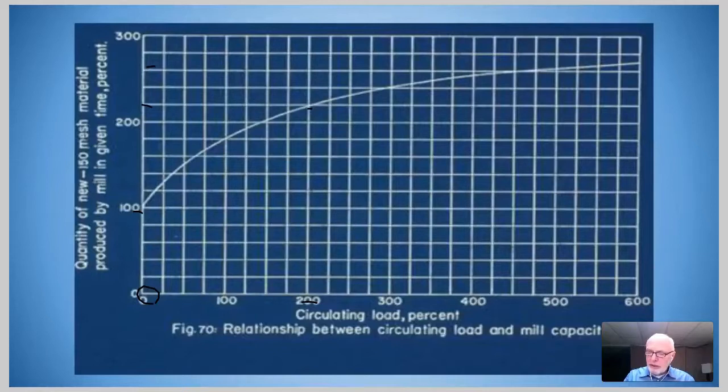Well, imagine a ball mill running an open circuit without any external classification equipment. A lengthy residence time is needed to grind all the way to the product size in one pass. The mill discharge itself would be 80% passing the P80 size. So at least near the discharge end of the mill, only 20% of the power is going to the grinding of coarse plus P80 size material, and 80% is being wasted. Depending on the size distribution of the mill feed and the back mixing conditions, an extremely large portion of the mill power is being wasted.